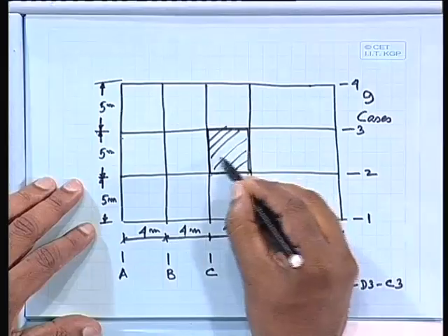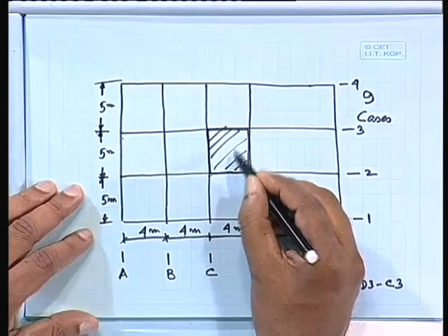Whenever you design, in your design calculation you are doing panel C2, D2, D3, C3. In our simply supported case we have only 2 values, the span moments, one along this side and another along the other side, that is, alpha x and alpha y.